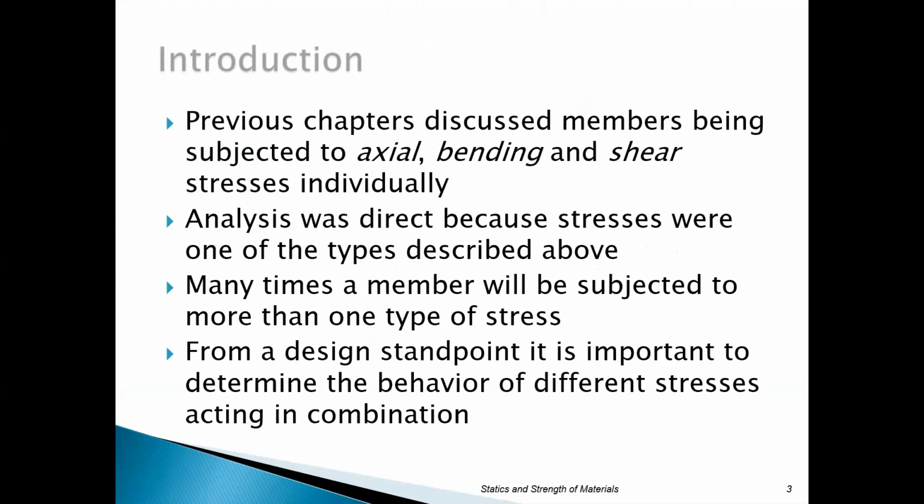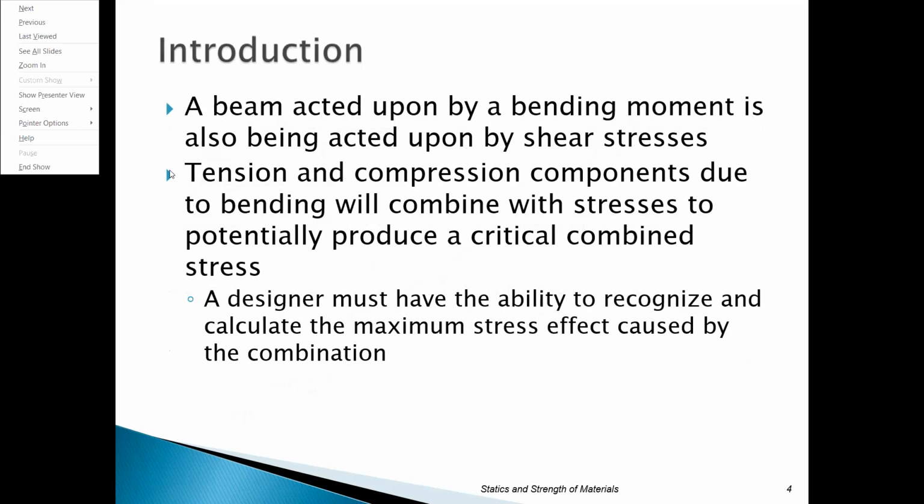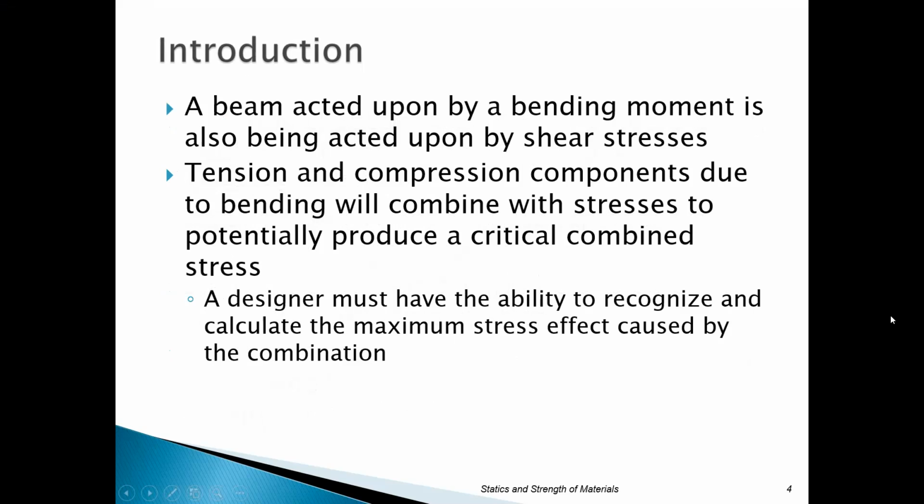Just briefly, the one thing we want to note is that there's more than one stress going on. Actually, you can have bending, axial, and shear stress going on. Instead of looking at those individually, you can look at them all together. Being able to recognize and calculate that is important, because the stresses at the top of the beam may not be the same as at the bottom, due to these types of stresses combined.